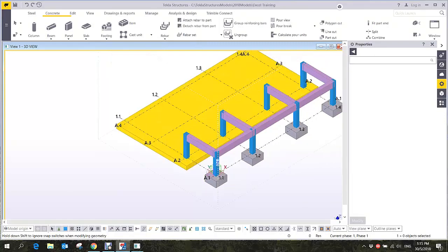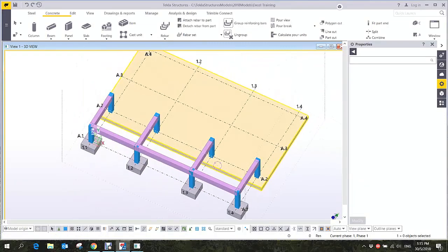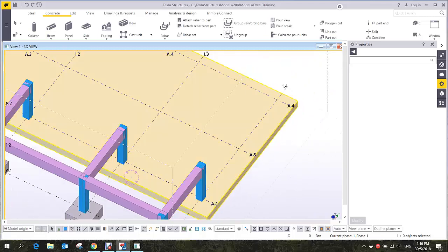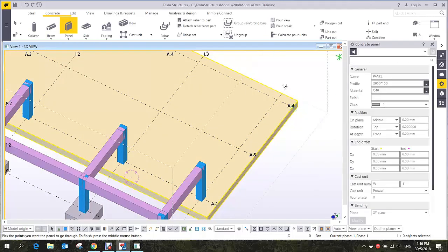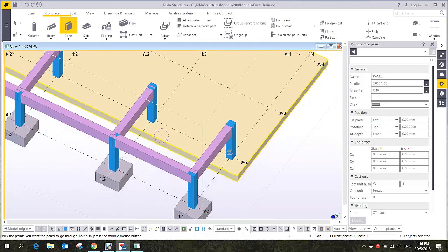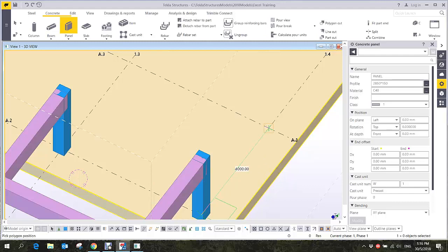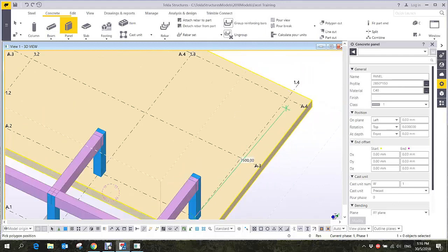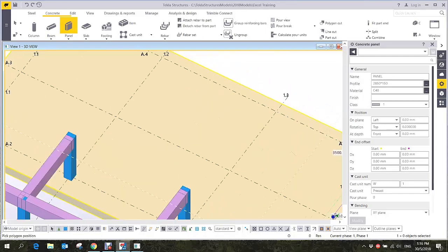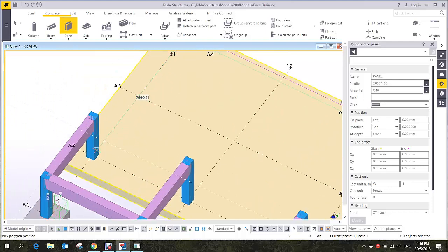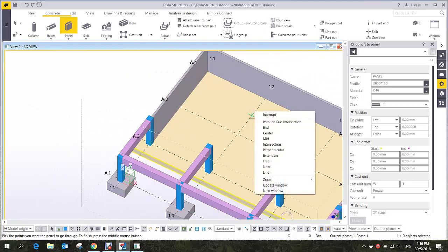And then let's add now the wall. Okay, so let's say my wall is this 2850 by 150, and then this time I'm going to change that one as a left. Okay, left, so that if I click on this one, 1 and then 2, or I can just simply click the whole thing, this, and then here. Okay, and then middle button of your mouse.